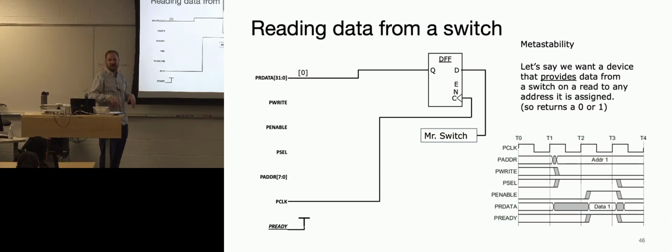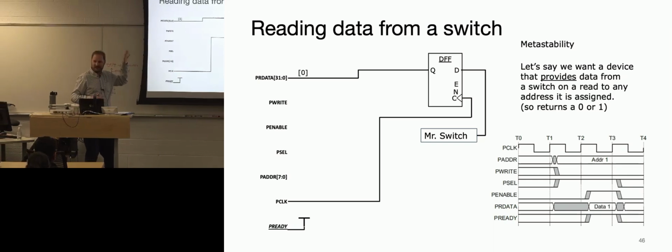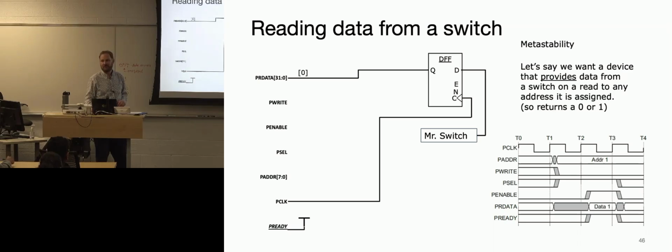The way we end up taking care of it, you'll learn about later, is you tell that peripheral to set an interrupt when the job is done. So an interrupt is just a signal that goes back to the core that says, hey, I'm done with a task, and it's asynchronous of the bus structure. So there's a mechanism, it's just that there's no queue or multitasking or anything inside these things.